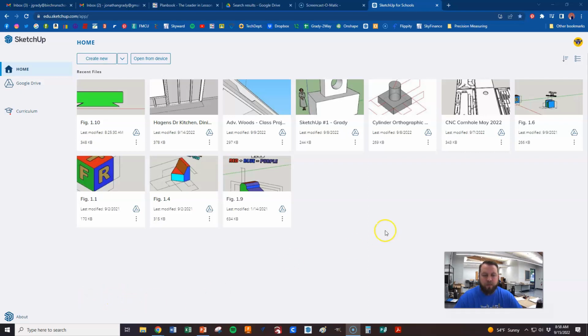Hi guys, back again with SketchUp part 3, and so we are going to start a new drawing, and we'll go up here to our drop down arrow, and what we're going to be doing is we'll select architectural feet and inches, and that'll open up a new window.